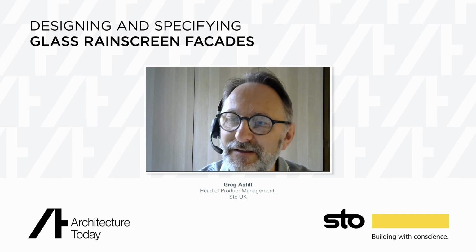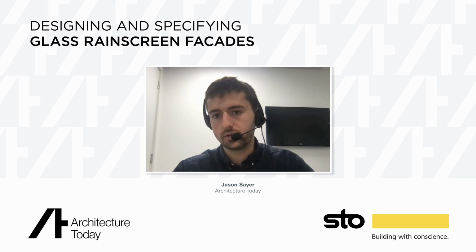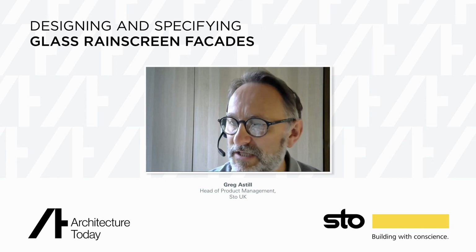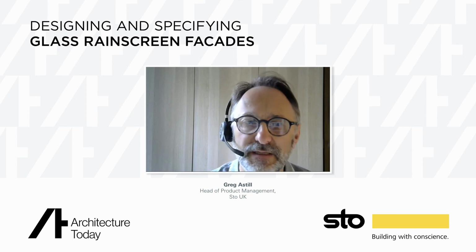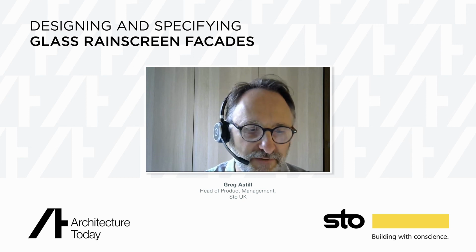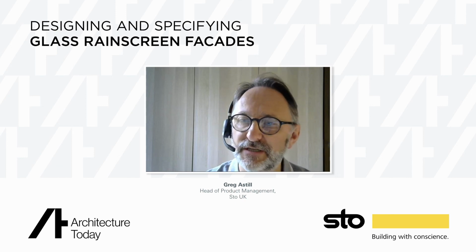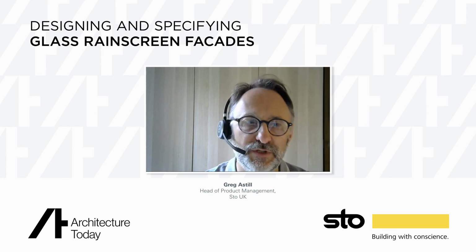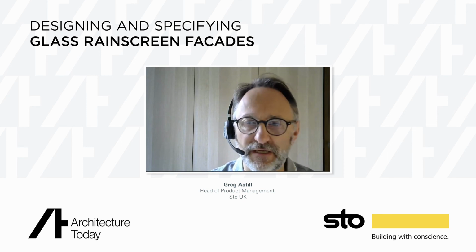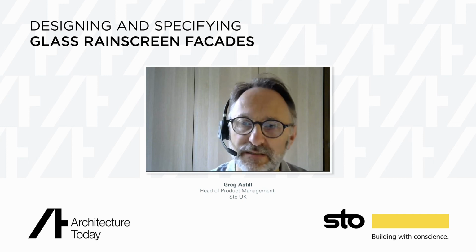How many are stipulated to be required per meter, or is that wholly dependent on the substrate and the design? That's wholly dependent on the substrate. Also the wind load that's anticipated. So we actually have a calculating tool which we've had developed by a firm of consulting engineers, which enables us to provide pretty good guidance as to how many brackets are required per square meter. Typically, you're looking at something like 2.5, 3 brackets per square meter in most cases.